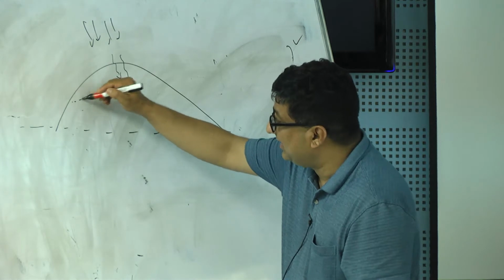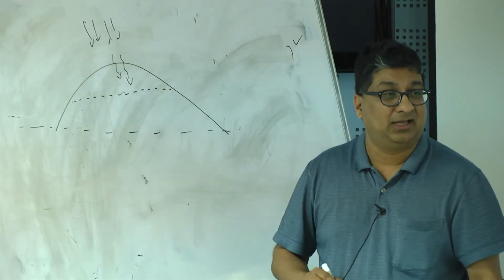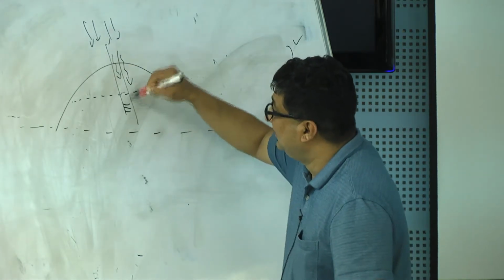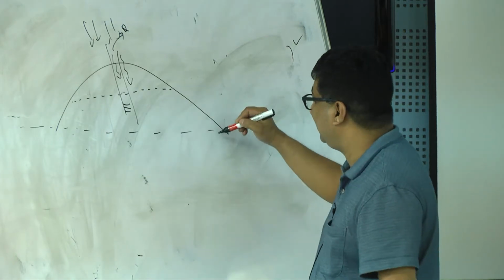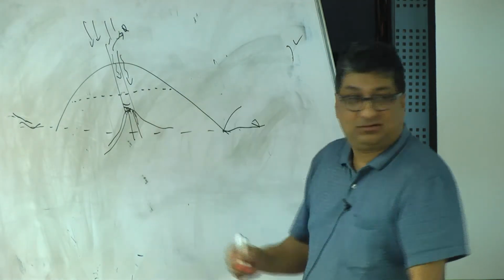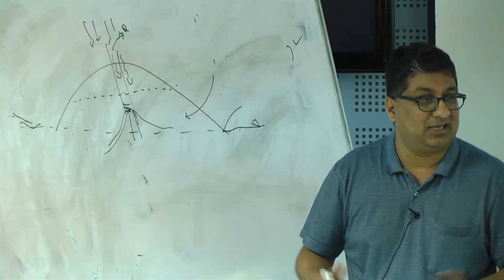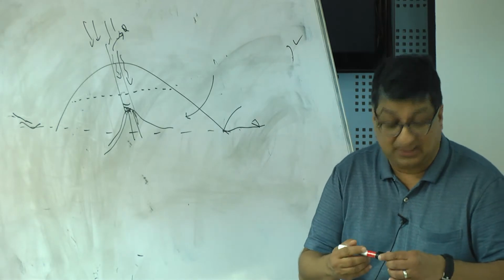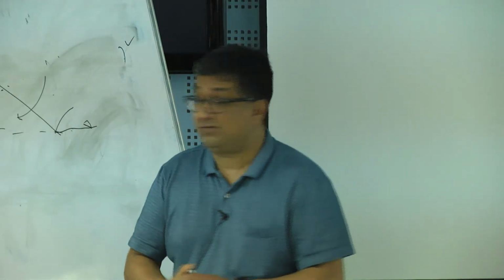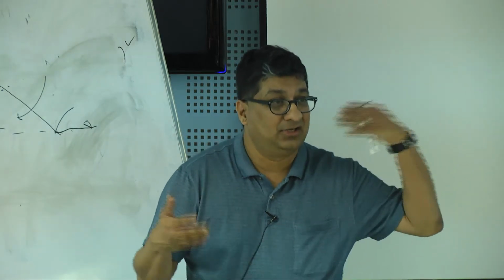So what will happen is it will create an aquifer that's actually fresh water sitting on top of salt water. Okay? Of course, salt water and fresh water are miscible substances, they're not immiscible. So if I put a well and I pump, okay, there is also salt water right here, right? This is my salt water, this is my salt water. So as I pump, the salt water will enter. Okay? And to make up for that, some of the salt water from the ocean will enter, and I will progressively salinize it. So there are small islands like Jamaica and other places, Hawaii. When the population was very small, they could sustain themselves on this fresh water because there was recharge, and their discharge was less than that recharge, and they were okay.